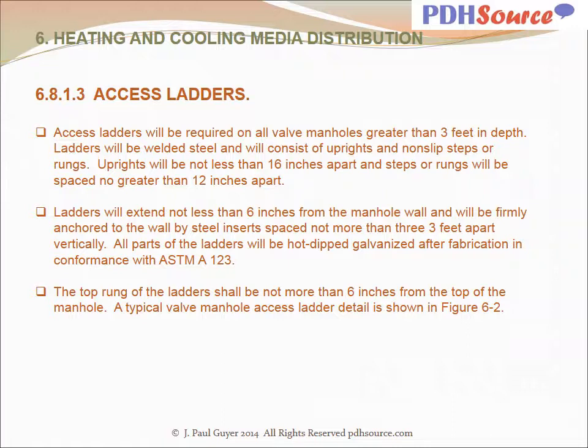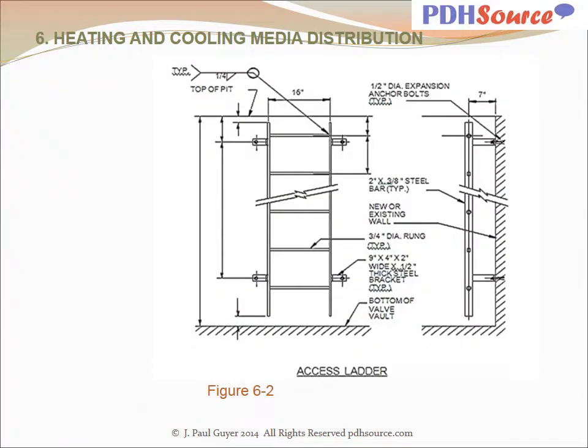All parts of the ladder must be hot dip galvanized after fabrication in conformance with ASTM A123. The top rung of the ladders shall be not more than 6 inches from the top of the manhole. A typical valve manhole access ladder detail is shown in figure 6.2. This is figure 6.2, a typical access ladder.